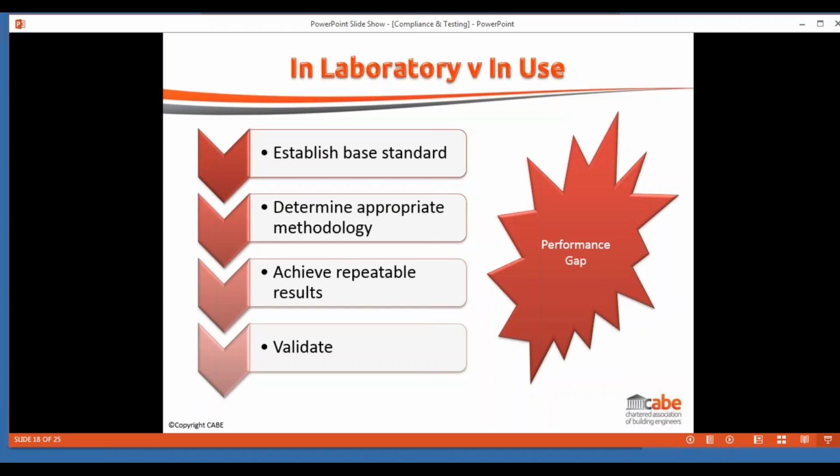So once you actually get a wind speed across a roof, the performance of it as a thermal element is going to be different than it might be in laboratory conditions. So some of it is using the laboratory as an indication, but not necessarily expecting that's going to be how the building is really going to work.